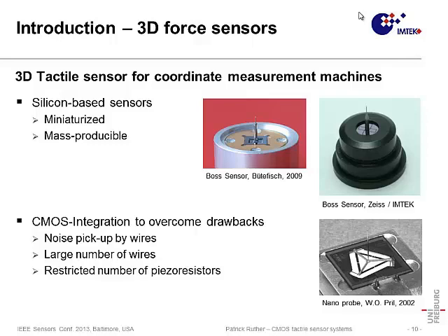And here in this example, we use a cross structure that is suspended through thin membrane hinges, and again, a tactile pin. Now, the disadvantage of all these three components is that you are somehow limited in the number of piezoresistors that you can integrate, or better to say, the number of leads that you can bring out if these are purely passive components, as it is here in this case. So, question, or the answer is quite clear. What if we integrate CMOS circuitry? Can we get rid of all these problems? And I would say yes, we can do.